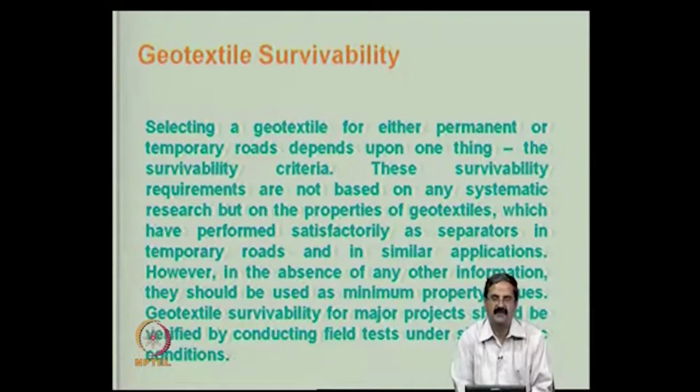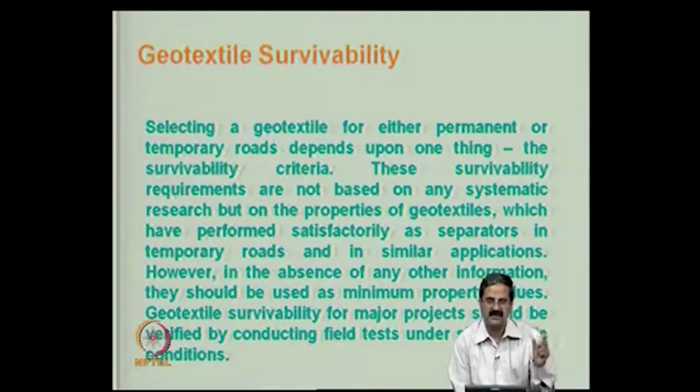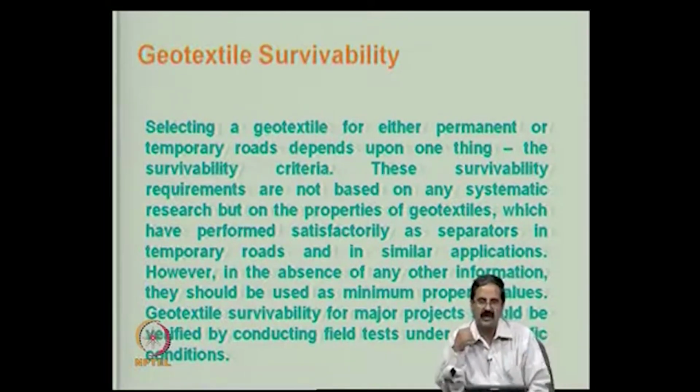Like we have seen in the case of filters and drainage functions, where we had a separate heading, survivability criteria, and they had certain specifications, like the grab strength should be this much, puncture strength should be this much. The specifications are drawn in such a manner that you do not have a difficulty in installing in the field and they do not get damaged in the field while doing things. That is it. So, if they are able to satisfy the requirements, it is fine, you can use it as a separator.